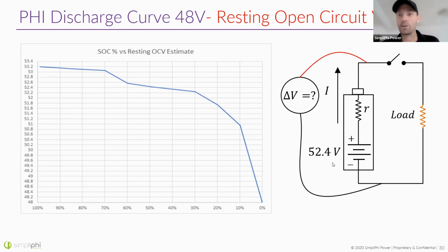Nova asks, does it work with microinverters like Enphase? Yes, with the appropriate inverter. Enphase produces an AC off of the solar panel. So as microinverters mount to the solar panel and produce an AC signal, you need an inverter that's capable of handling AC to invert that to produce DC to charge a battery. Our inverters do it. SolarArk inverters do it. A number of inverters are capable of doing this. So yes, our batteries can work with Enphase.